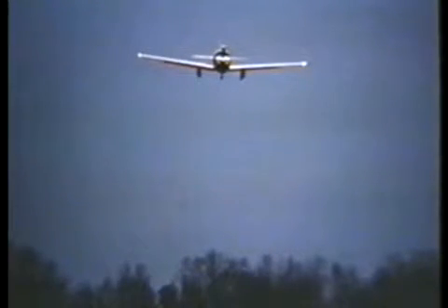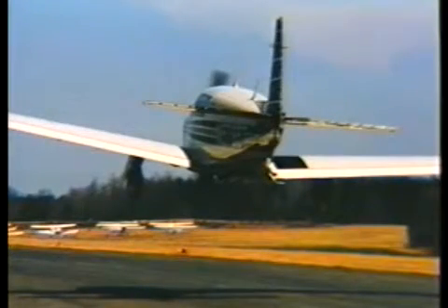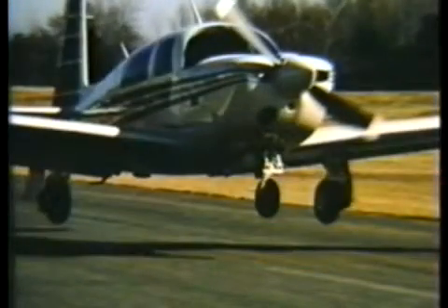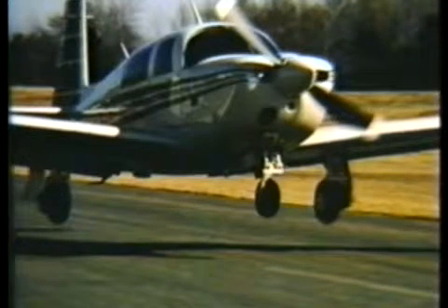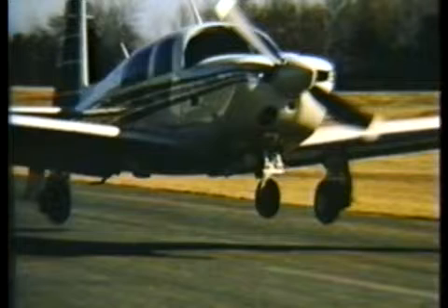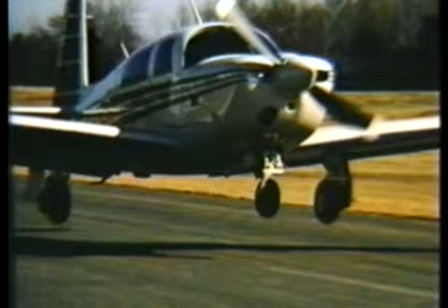Now let's make everything exactly the same, except that in this second example, you've been tooling around by yourself all day, so your landing weight is much lighter. But you still opt to carry the same short final approach speed as before, 1.3 VSO at max landing weight. And lo and behold, your intended point of touchdown whizzes by beneath you. Why? Because you're still floating in ground effect. And why are you still floating in ground effect? Because you came in light, at a lower landing weight, but you were still flying your approach based on VSO at max landing weight. So your airplane flew merrily down the runway.